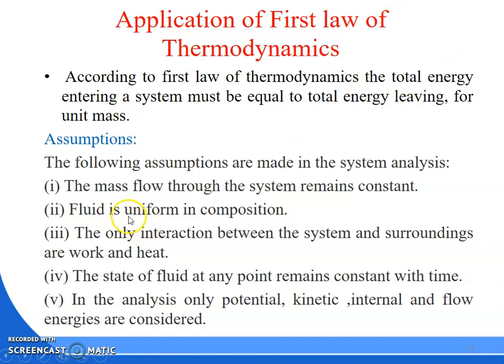So what are the assumptions? The following assumptions are made in the system analysis. First, the mass flow through the system remains constant. If mass interaction is there, it is an open system, so mass in should be equal to mass out. Fluid is uniform in composition. If you are giving heat, the fluid composition should not change; it should maintain chemical equilibrium.